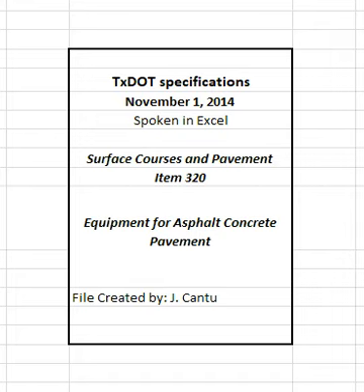2.3.1.1 Tractor unit. Supply a tractor unit that can push or propel vehicles, dumping directly into the finishing machine to obtain the desired lines and grades to eliminate any hand finishing. Equip the unit with a hitch able to maintain contact between the hauling equipment's rear wheels and the finishing machine's pusher rollers while mixture is unloaded.